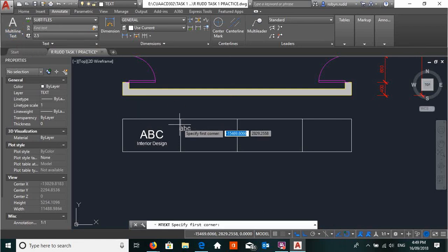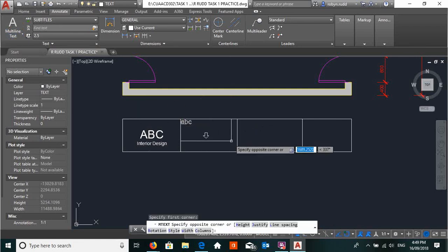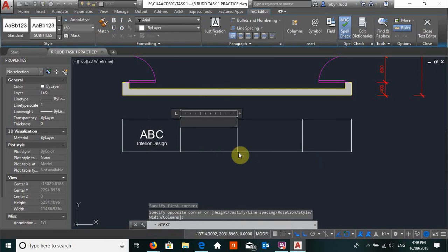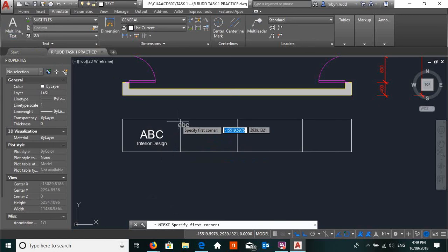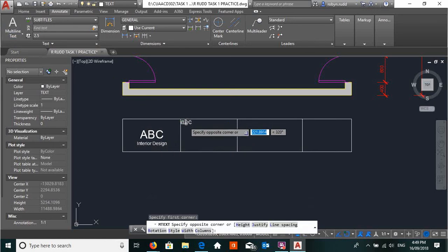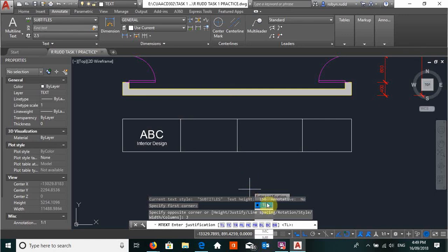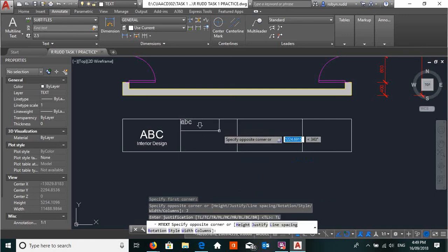Multi-line text there, and let's go down here. I'm not concentrating. So subtitles we're in, multi-line text. Let's do that. Click once, drag, and we go to justify. So that tells us where we can start writing. And I want it as top left because I want to write in the corner here.